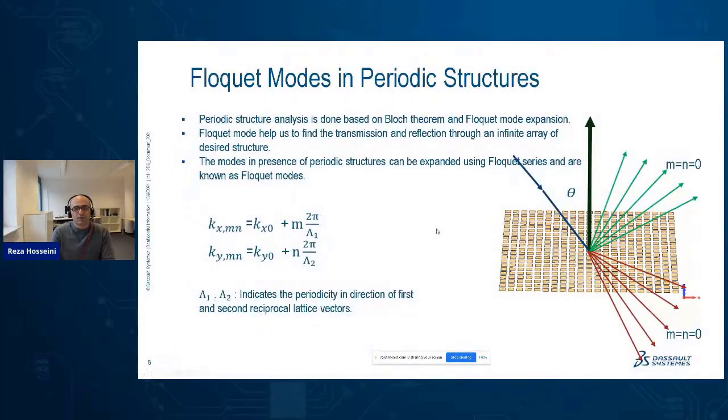Before getting into the infinite array, I would like to have a quick overview of the Floquet-mode analysis. When we have periodic structures, the phase relationship between the incoming wave and the diffracted or scattered waves can be written based on the Bloch theorem.